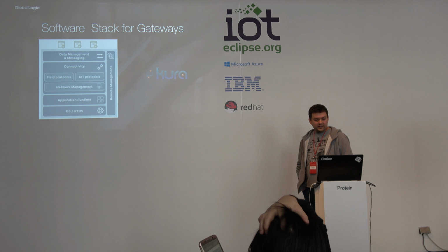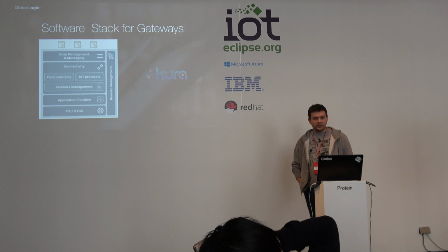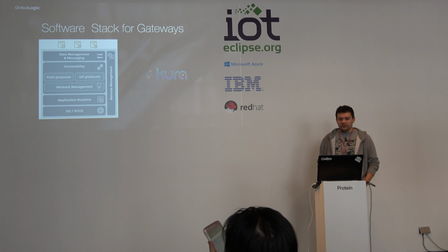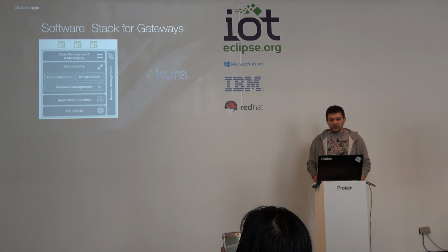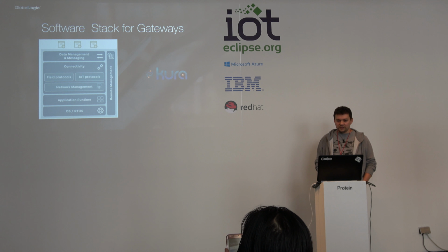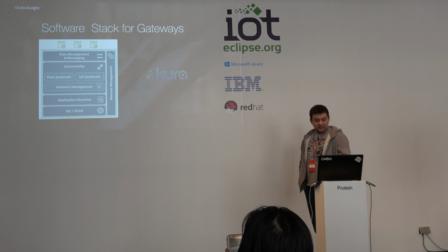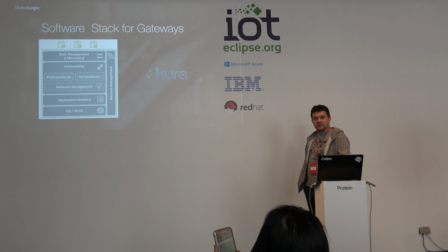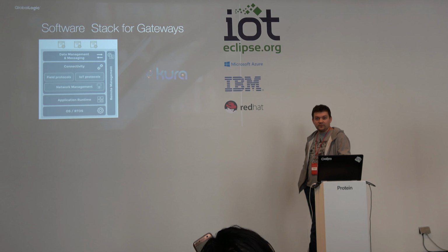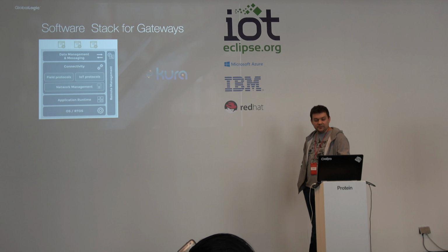Also, Kura provides really good network management. So if you would like to establish a secure connection or to start with your local network really fast, it allows you to configure everything from the configuration UI. Additionally, for my purpose, Eclipse Kura is bundled with the Modbus field protocol bundles, so it was very easy to start communicating with, for example, this PLC.